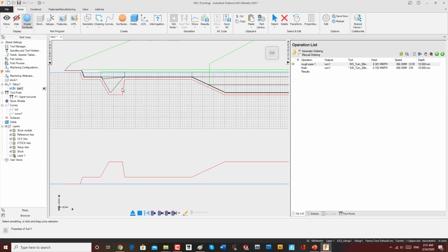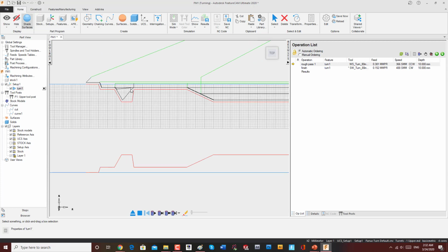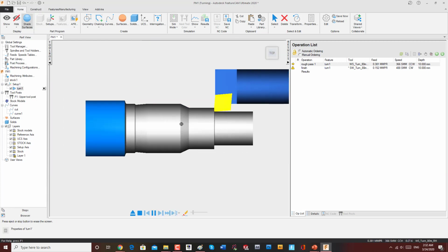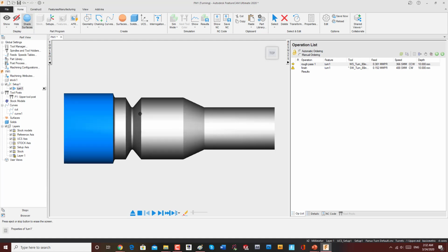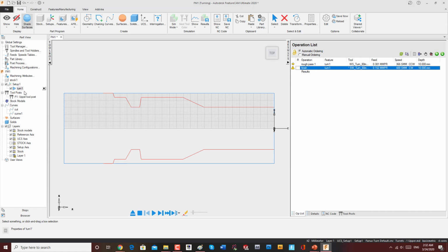Can you see here? This one, the angle is incorrect. This cannot fit. That's why the tool is showing you this message, because the tool cannot fit. So we have to finish this one in 3D, and then you will see when we change the tool, also the new tool cannot fit properly. That's why it shows you like this for finish. What you have to do is either again create, change the curve, or change the cutting tool, or simply change the curve. This curve is incorrect.